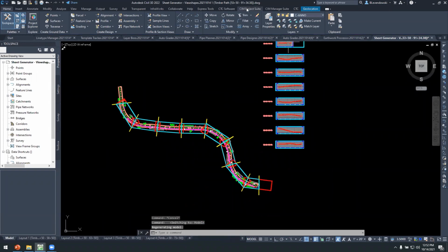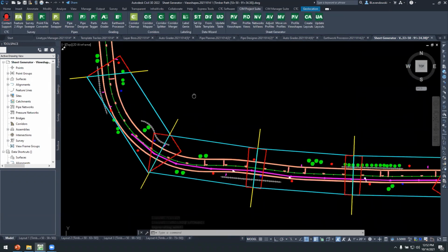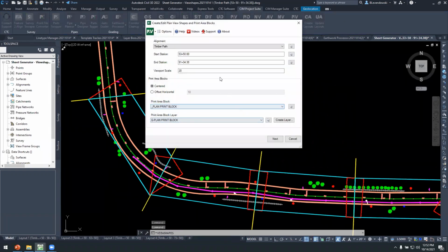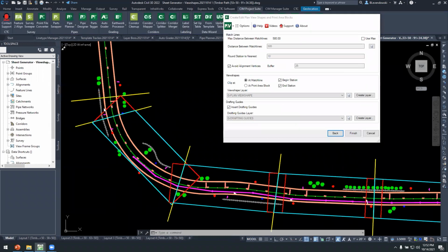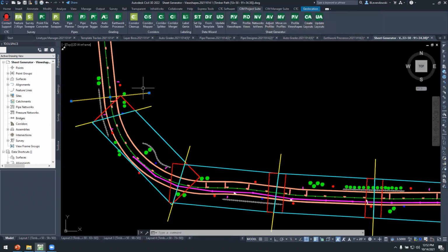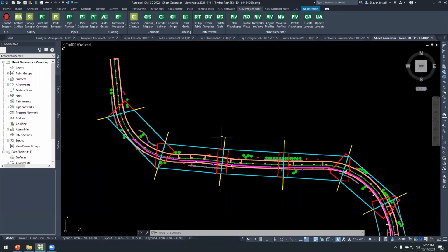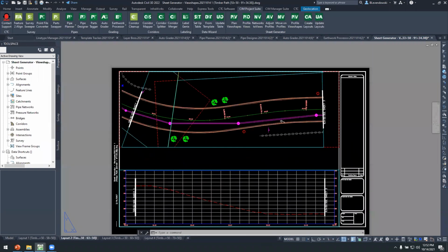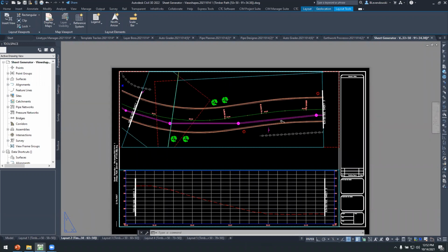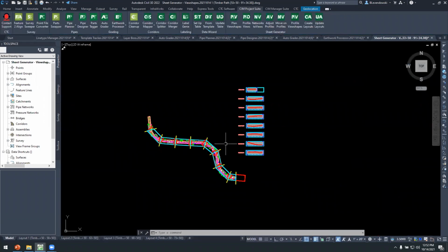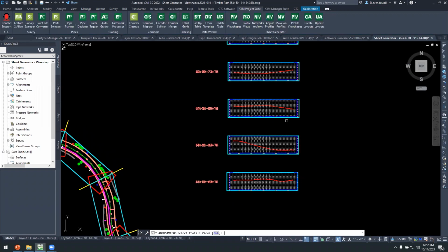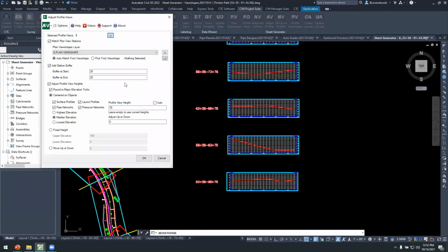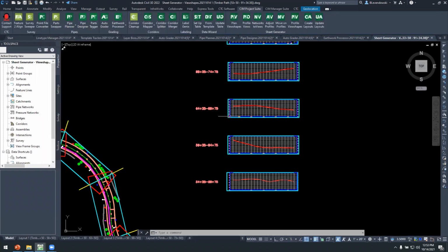All right, let's make a shift, right? Let's say all of our plan views shifted because the project extents change. Let's go back to that 5450 for a starting stationing. I'm going to click next and finish, and it shifts all my sheets, right? It could have been a station change. Maybe I just needed to shift all the sheets. But if we look in here, my sheets, everything's out of place now, right? I've got to update my profile views. No problem. You just run through the same tool set, grab all those profile views, and adjust those to the new stations and elevation ranges.